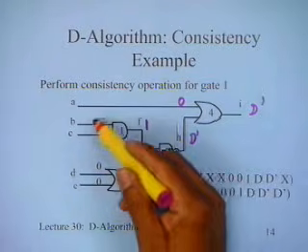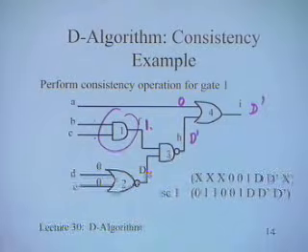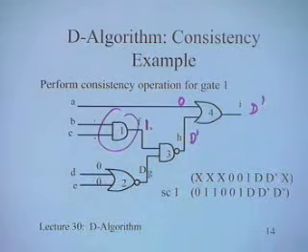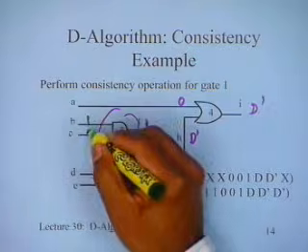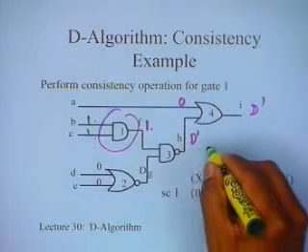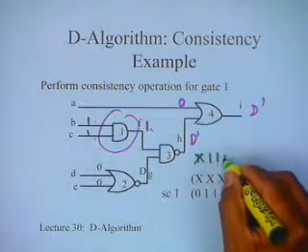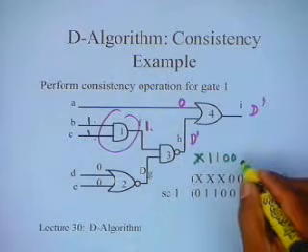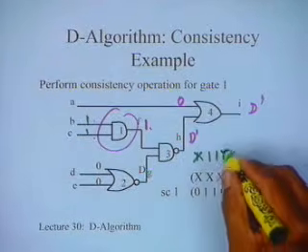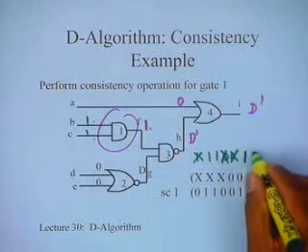I want to assign the inputs in such a manner that I am able to generate an output of 1. If I look at my singular cover for the AND gate, the only entry which generates the output of 1 is 1 1. So the SC is don't care, 1 1, 0 0, don't care, A B C D E F, F is 1, and then don't care.